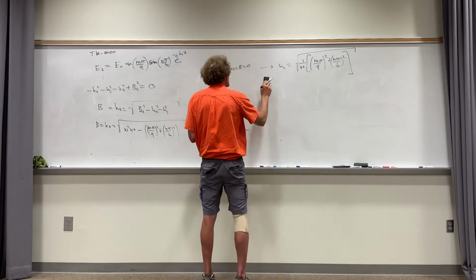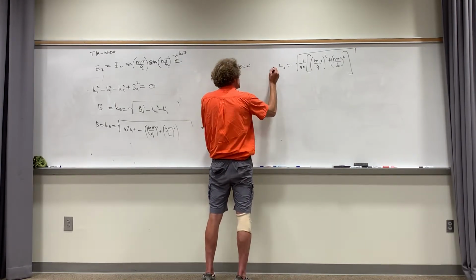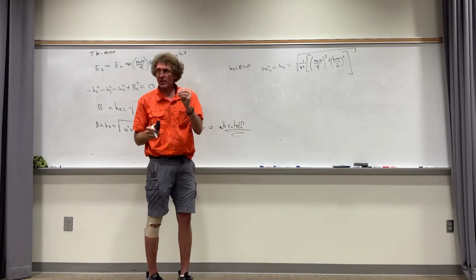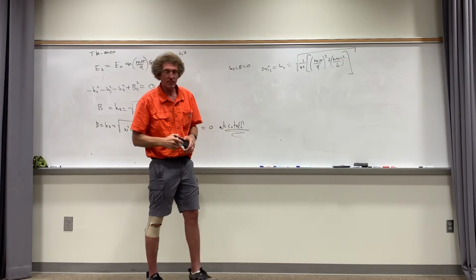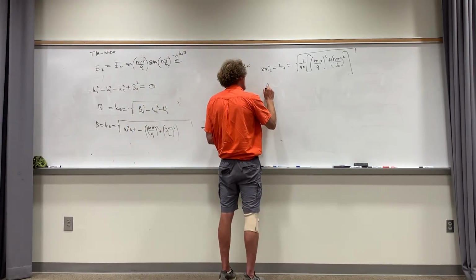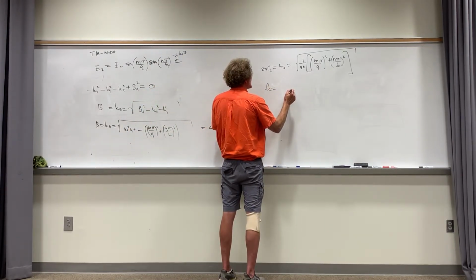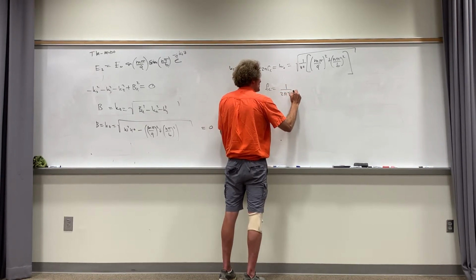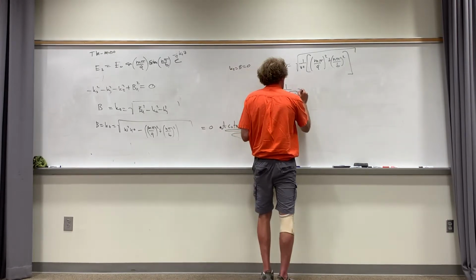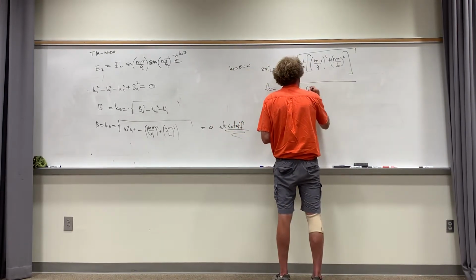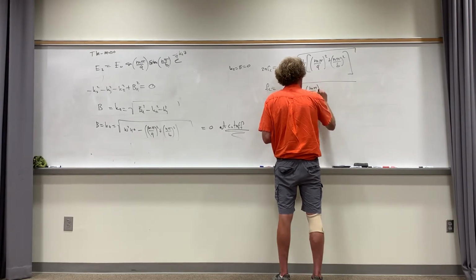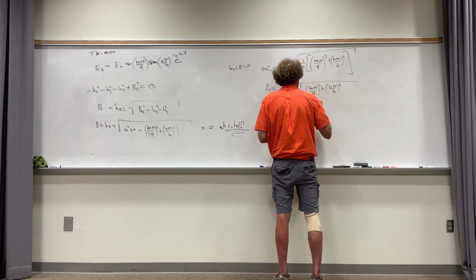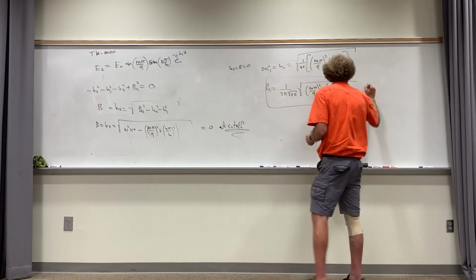But what is omega in terms of f? People? 2 pi. It's equal to 2 pi f, right? And that f would be f cutoff. It would be the frequency below which I couldn't propagate a wave. So then I can write f cutoff as this. I can say it's 1 over 2 pi times the square root of mu epsilon in the guide times the square root of m pi over a squared plus n pi over b squared. And this is the cutoff frequency in a waveguide defined.